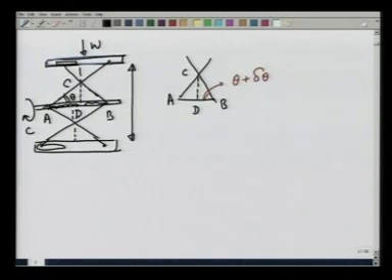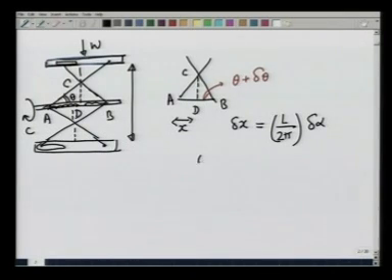So, let us calculate that. Let us call this distance AD x. So, that delta x is the reduction in the length, and delta x is going to be L over 2 pi times delta alpha, where delta alpha is the rotation of the screw.